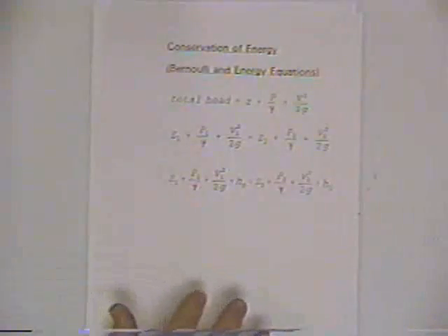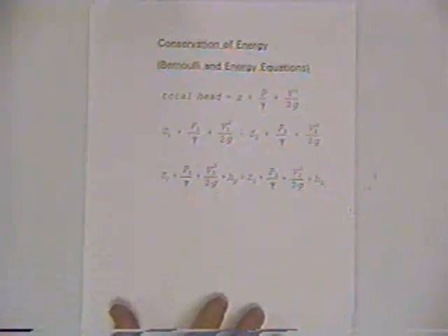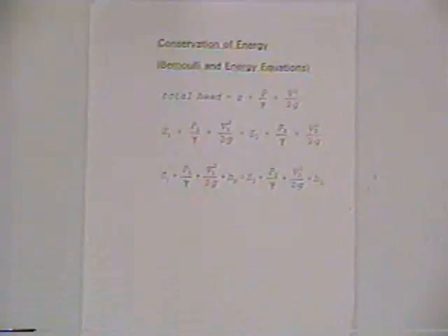And this is a real workhorse in fluid mechanics that we'll solve a lot of problems with. As we solve problems, often we'll combine conservation of energy with conservation of mass. And so the basic concept of energy is that, in engineering applications, we like to talk in terms of head. We went to the basic derivation of the Euler equation.